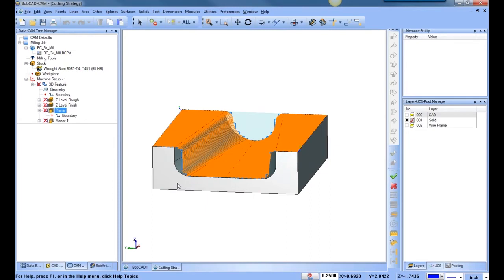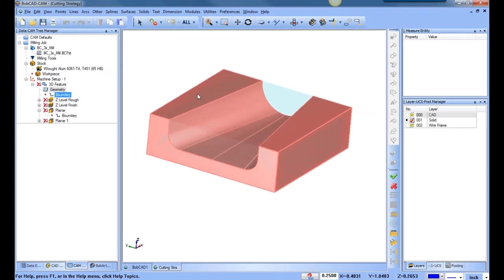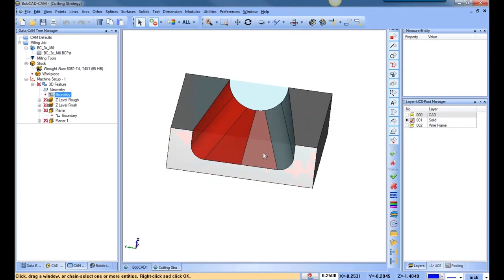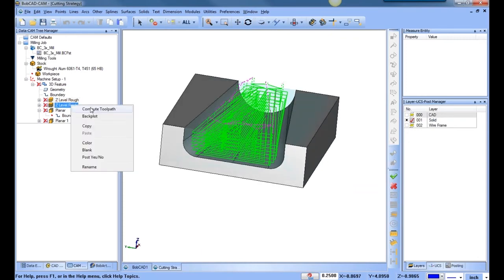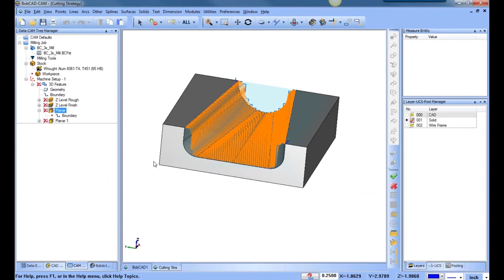Versus when you try to pick off individual surfaces. When you try to pick off individual surfaces, generally that's where you're going to run into the tool making contact with other areas of the part, okay? Now, some of the things we talked about as far as boundary control, we did pick a single surface there. If you pick multiple surfaces as a boundary, that's what I'm doing right now, the result is generally not what you're expecting it to be. It's very inconsistent as far as the results that you're getting. So if you're trying to select surfaces as a boundary and you're using multiple surfaces, I really just don't recommend it, okay? What I generally recommend is wireframe as a boundary, or surface edges.